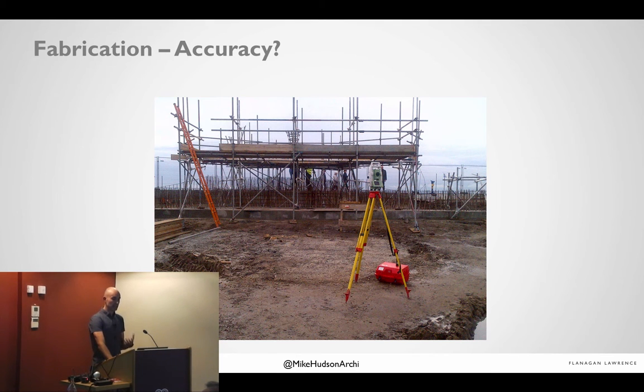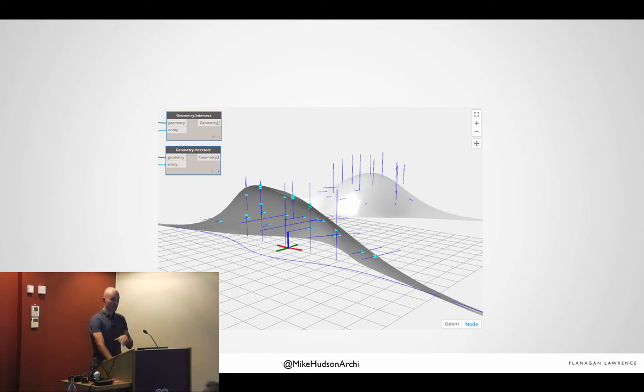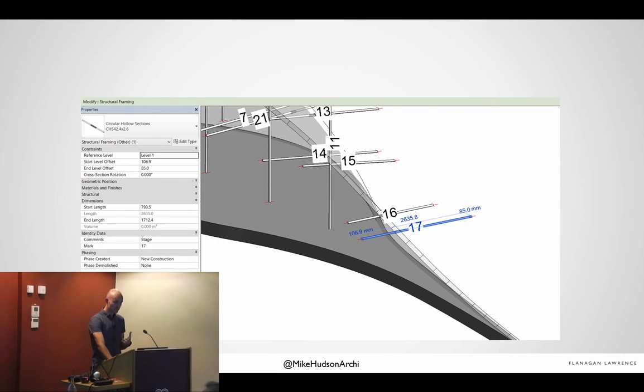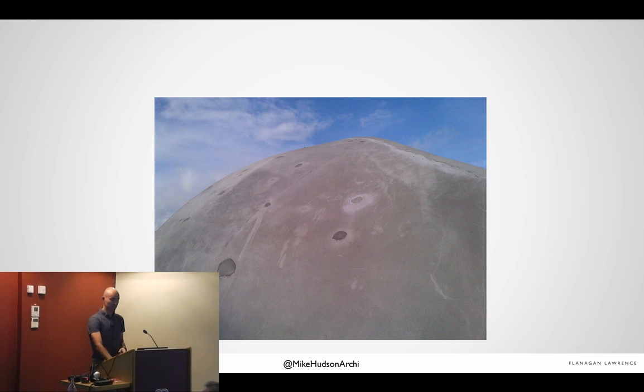So what we did was we laser scanned the formwork scaffolding that the fabricators had put up, and then rebuilt that inside Dynamo so that we could understand where the actual scaffolding poles were crossing over the form that we had. Then, first Revit shot for you, we itemised all of those individual pieces of scaffolding, and that's the outcome. It's almost like a random selection of interfaces inside the surface, but we had a surface variation of less than 2 mil outside of the original design intent. So that meant it performed structurally, but it also performed acoustically, which was much more sensitive to the surface quality than the structural side.